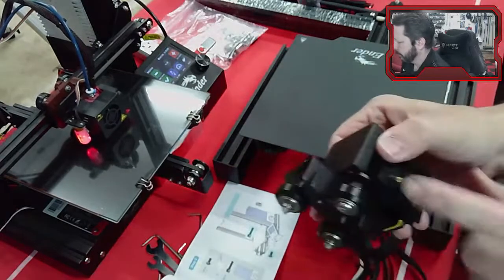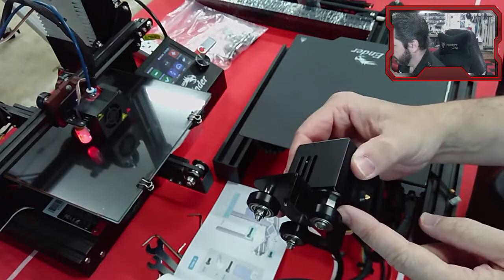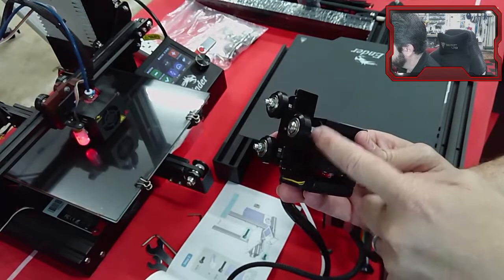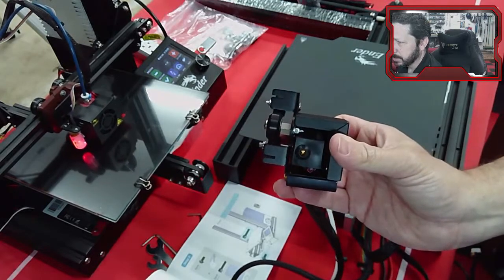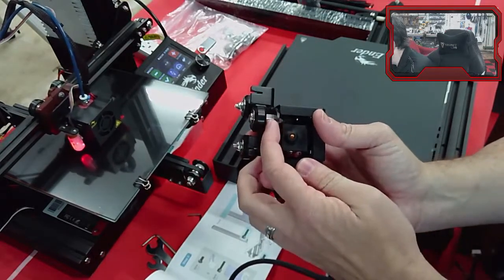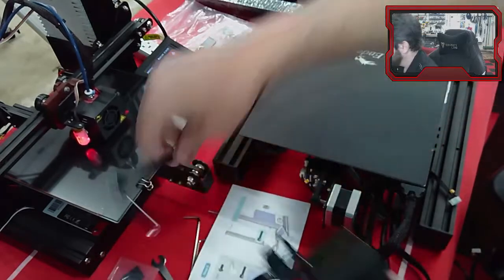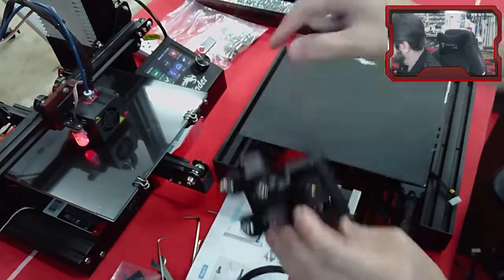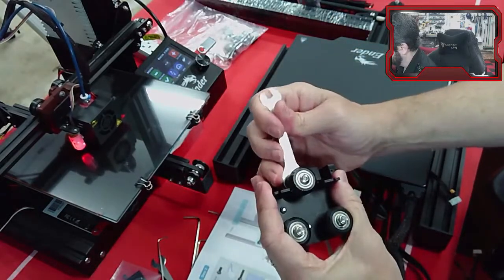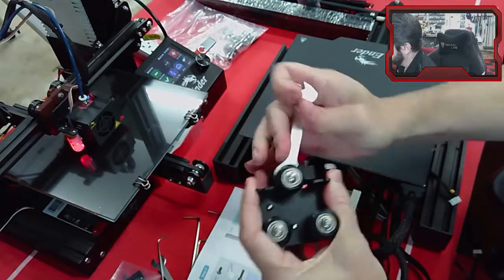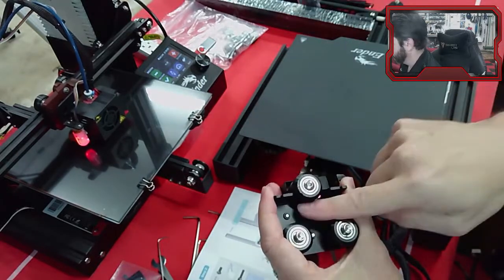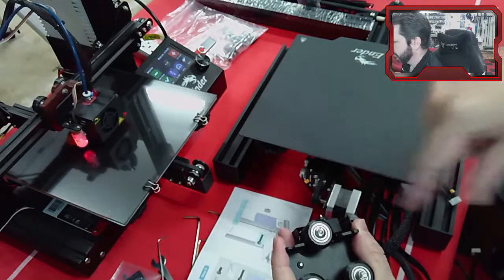Actually, let's do it on this one. This one right here is an eccentric nut. You might even pick up how the bolt center is not aligned with what you would think the center of this shaft is. With those thin wrenches, if something's loose, you can turn this eccentric nut. Let's see if we can make it happen. I don't know if you can see it, but as I turn it, this wheel is moving in and out depending on which way I'm turning it, and it will ride against the rails closer or further away.